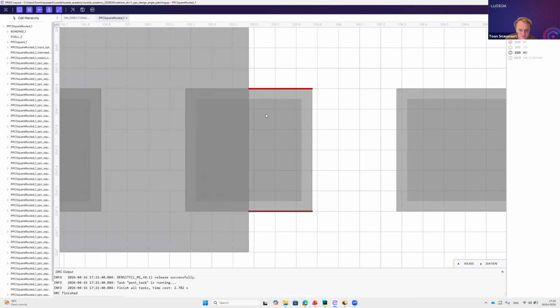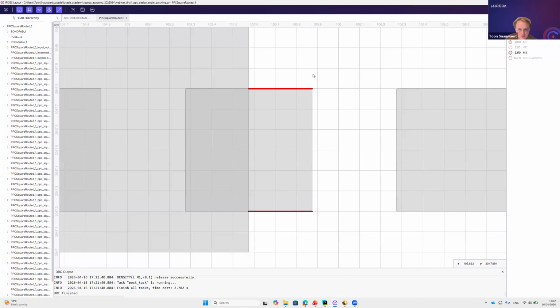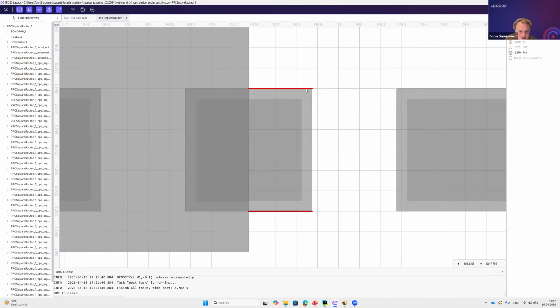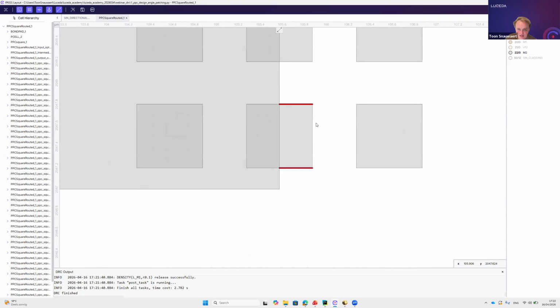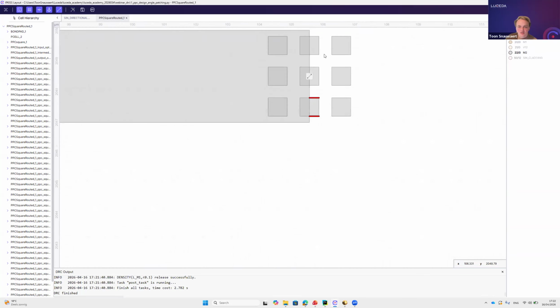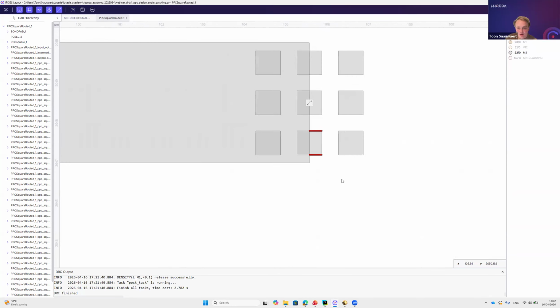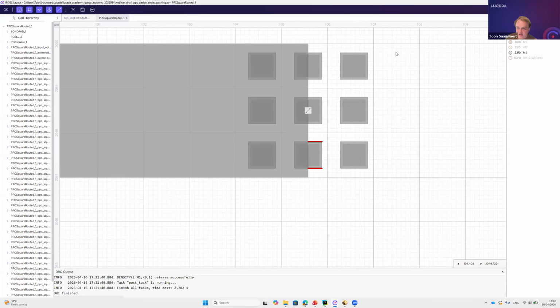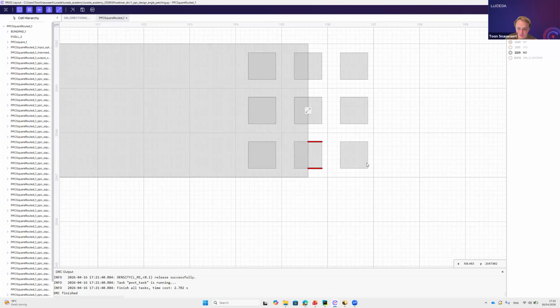And now I can have a look and I see that indeed 1 micrometer goes here from 105 to 106 and it's below 1 micrometer. So we need to create vias that are bigger in order to meet the foundry requirements. For that, I will create a bigger via cell, but I will make sure that the via array still has the same area.